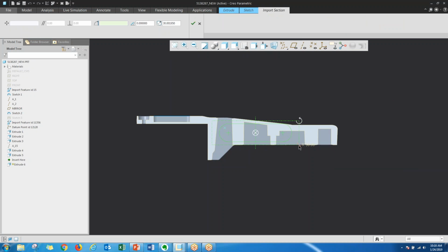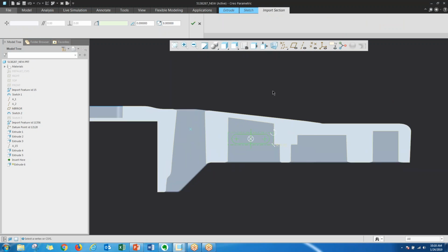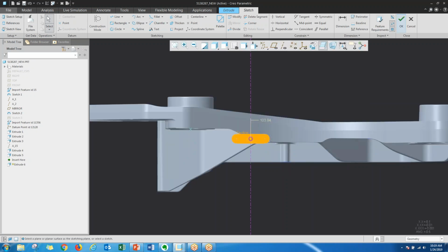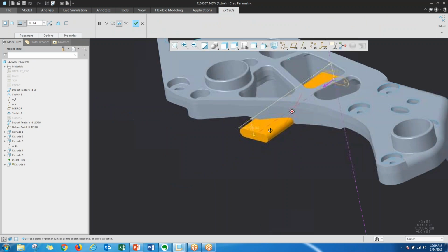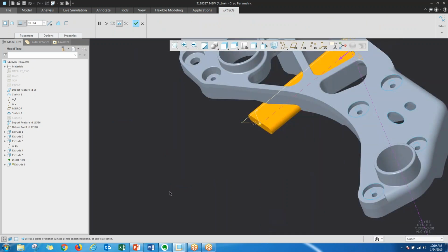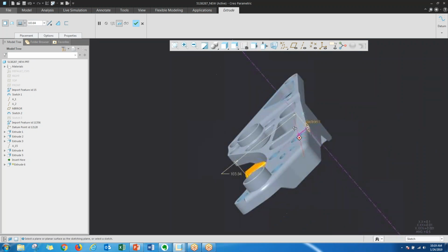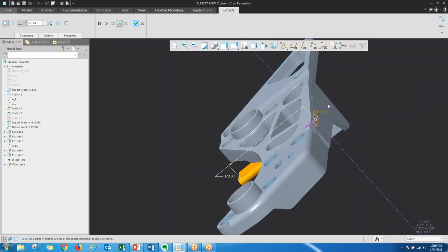And I'll close this out. And let me scale this down to a nice even number there and finish out importing. All right, so I'm not going to worry about dimensions for now. Let's go ahead and say OK. And now I have my extrusion. Let's say I do want it to go through the back surface of my bracket.